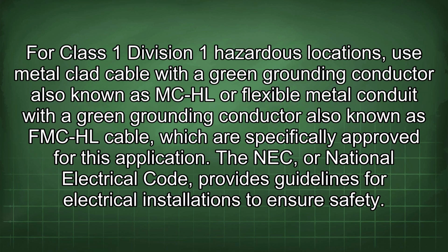For Class 1 Division 1 hazardous locations, use metal-clad cable with a green grounding conductor, also known as MC-HL, or flexible metal conduit with a green grounding conductor, also known as FMC-HL cable, which are specifically approved for this application.